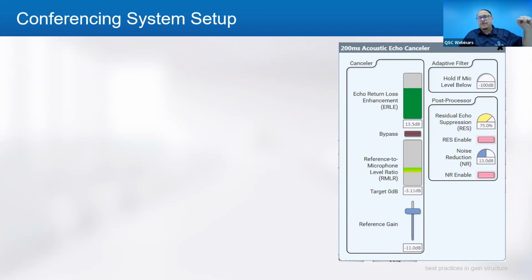And whatever that value is sitting at, so if it's at -53 or 57 or whatever, that's about where you'll start your adaptive filter. So you'll set it there. And so the idea is when you mute the microphone prior to the echo canceller, which is not best practice, but sometimes unavoidable, if you mute it prior to that and then unmute, there shouldn't be any 15-20 second lag of convergence time that needs to happen there. So that's kind of how you set that up.